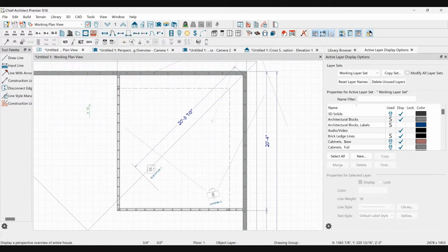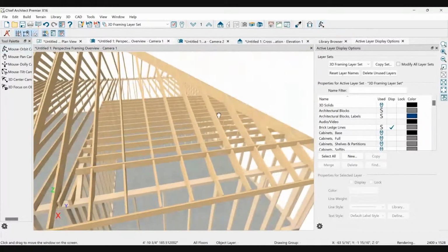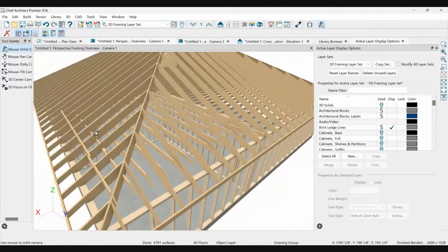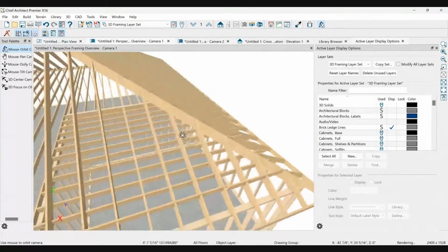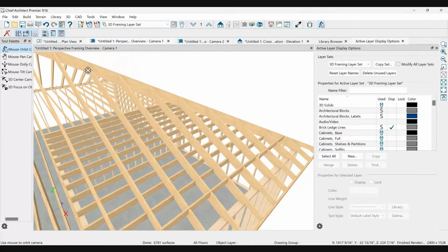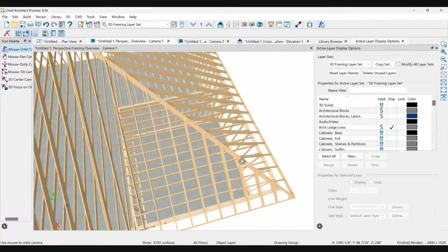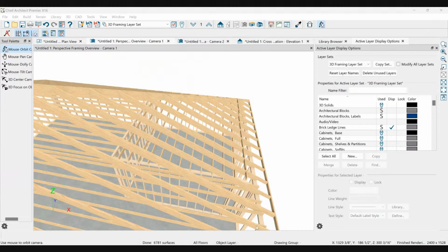Let's take a look back inside the framing. So it's when you have a situation like this where you can't put a beam supported on either wall of an outside room because of the weird ceiling raise, and you just have a really long spanning hip. Because what is this hip? The hip is a beam. It's just going up at an angle, and it's carrying all the weight of all these rafters that are sitting on it. So I hope that answers your question.